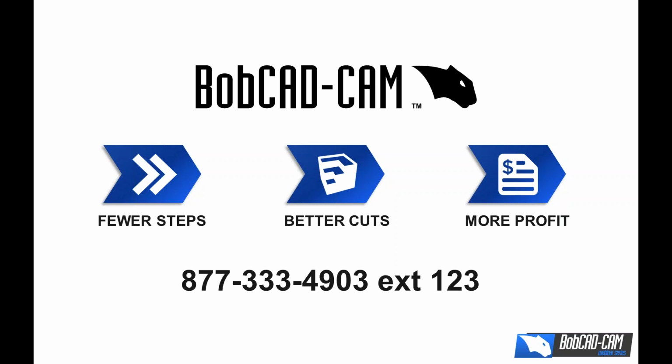All right, so I have a solid model here. There's a couple of different holes. At the beginning of every job, it doesn't matter whether you're drilling, profiling, or pocketing, the first thing that you need to do is to create a job. So we're going to go to the CAM tree, and then we're going to go create new job.